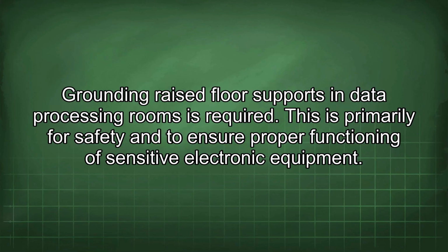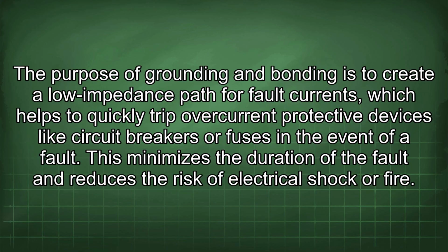Grounding raised floor supports in data processing rooms is required. This is primarily for safety and to ensure proper functioning of sensitive electronic equipment. The purpose of grounding and bonding is to create a low impedance path for fault currents, which helps to quickly trip overcurrent protective devices like circuit breakers or fuses in the event of a fault. This minimizes the duration of the fault and reduces the risk of electrical shock or fire.